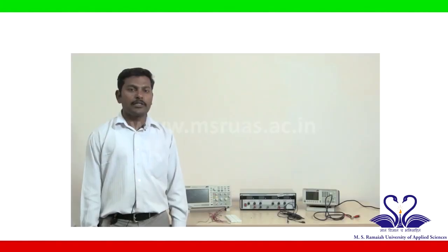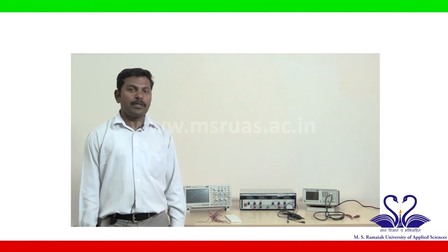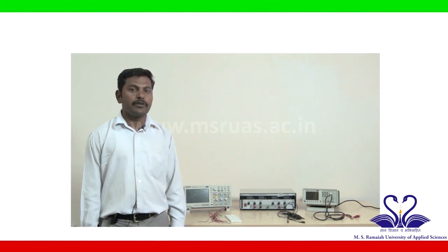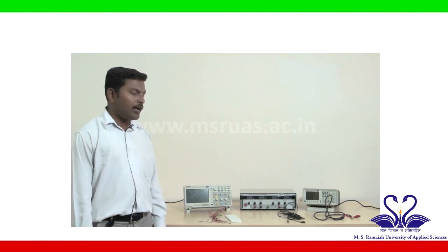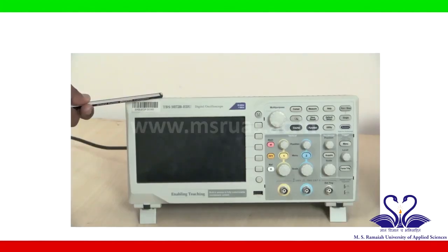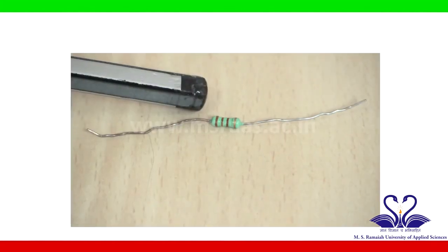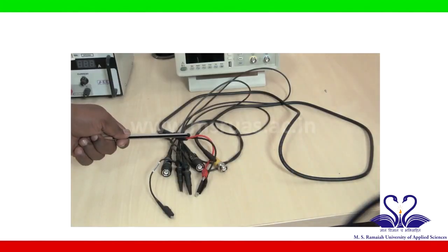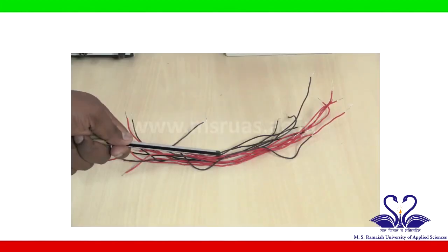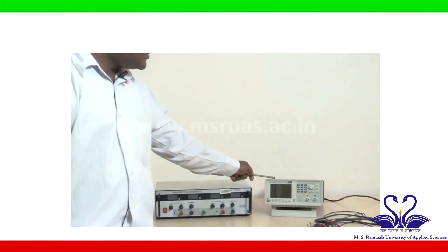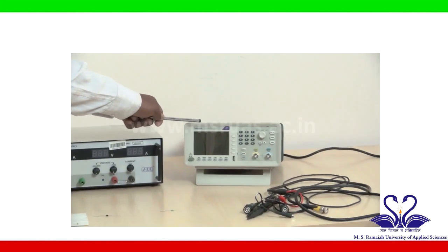Hello students, experiment name is Clipper circuits. Aim of the experiment is to observe the output waveform of a positive shunt clipper circuit, the output waveform of a negative shunt clipper circuit, and the output waveform of a positive series clipper circuit. Components used for the circuits are digital oscilloscope, dual DC power supply, function generator, diode, resistor, probes, breadboard and connecting wires. Before starting the connections, let us see the different components used for the experiment.